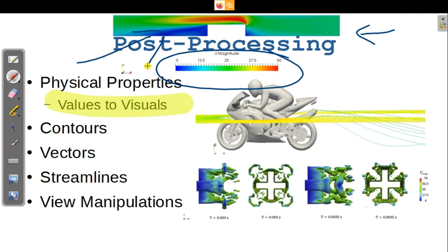And if you see the picture below, this is the bike. I have plotted streamlines on a horizontal plane. To plot streamlines, you take the velocity values and convert them into streamlines, and wherever you want in your domain you select injection points and allow the streamline to move through that point. Based on forward integration and backward integration in your post-processor, the molecules start moving based on the flow field data, that is velocity data. With all the XYZ points, you will be able to draw this streamline.